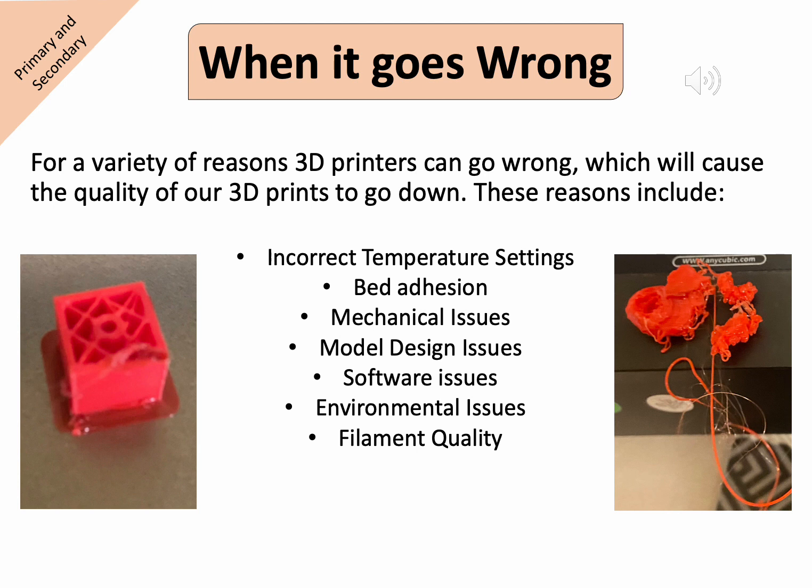It also could be things like dust on the build plate, or other issues such as gunk on the plate or other things of that nature. Mechanical issues could also occur if some of our parts fail, such as our nozzle, our heating elements, our stepper motors, etc.